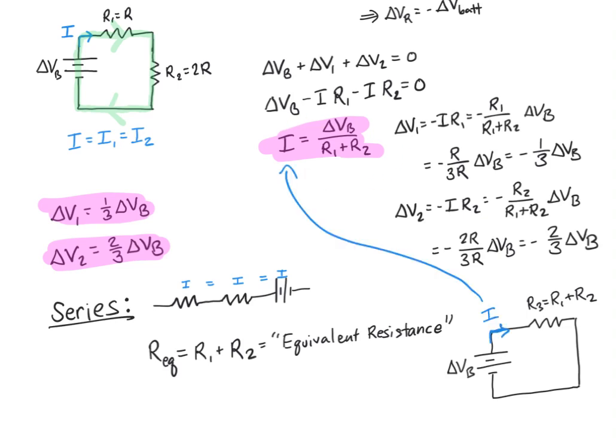So replacing R1 and R2 with their combined equivalent resistance results in essentially the same circuit. This is actually pretty useful if you're building a circuit because you might not have access to an infinite number of different values of resistances. You might have to piece together the resistances that you want in your circuit based off of a finite number of options. By combining resistors in different ways, you can achieve different amounts of overall resistances for different currents flowing